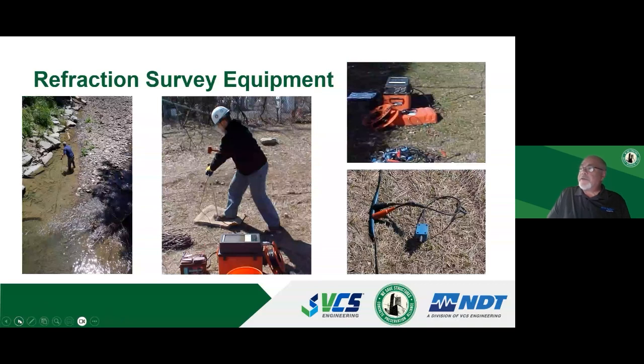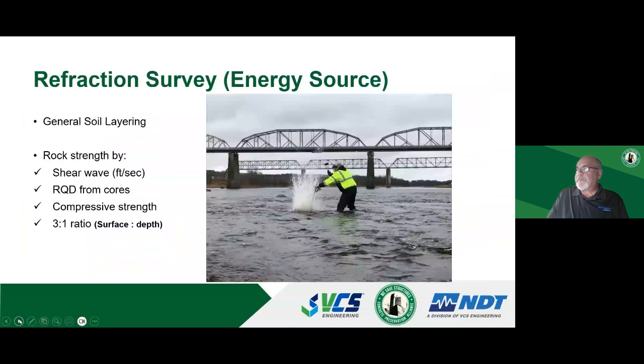In the upper right is all of the equipment. It's powered by a battery, so very portable. And the cables are in the foreground there. The lower right image is a geophone that is stuck with a small spike into the ground. It's basically a magnet that is suspended on a spring and connected to the electrical cord to determine the time differential from when the energy impact takes place.